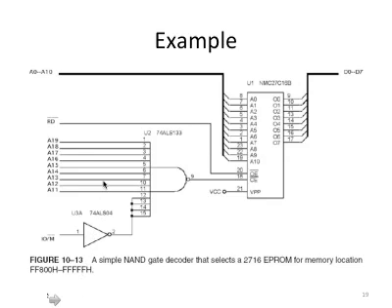That is to say, all these inputs to the NAND gate are ones. Also, at the same time, because this is a memory read operation, this is going to be a 0. You have 0 as the input to the inverter, so you have 1 coming out. So you have all ones on these 13, 14, these inputs to the NAND gate.